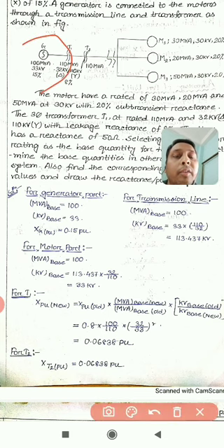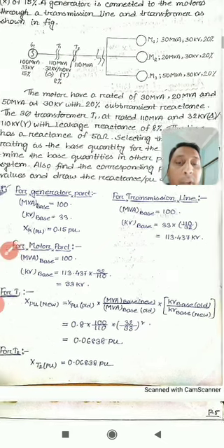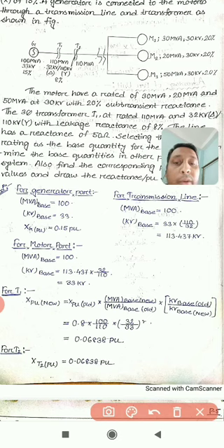So we will go one item at a time, starting with transformer T1. For a transformer you have flexibility. You can think of the transformer on this side or on that side. But if you consider the T1 side, this side, then you have to take this side's system base. You can see the old per unit value is already given as 0.08. We saw a long formula yesterday, old, new, old, new, so we are using that formula. Go to the new value. So new is this one.